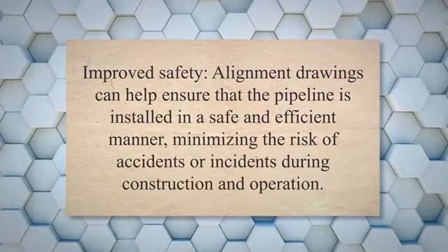Identify the scale and orientation. Determine the scale of the drawing, which will typically be indicated in the title block or legend. Also, identify the orientation of the drawing, which will indicate the direction of the pipeline route.